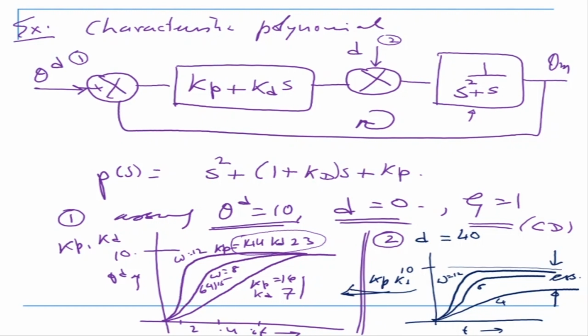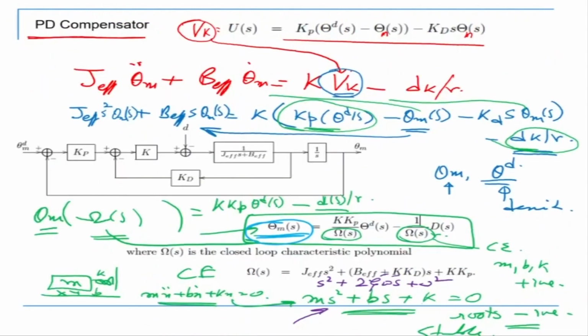Okay, so this basically shows us how you design a control system. When you say PD controller, what does a PD controller actually mean? When we say control system design, it basically means I need to find what is this Vk. This is my controller. If it's a PD controller, I design my PD controller, put it in here, then find the characteristic equation, look at the stability of the characteristic equation, and then look at the steady state error. That is the meaning of it.